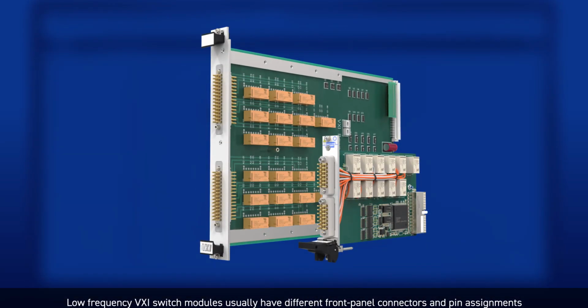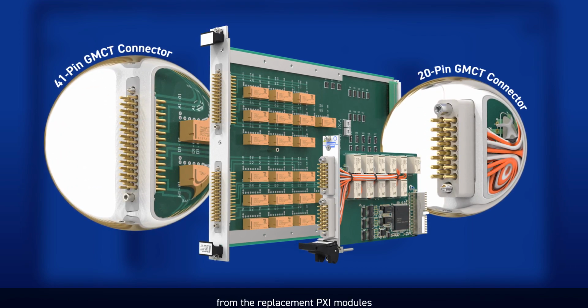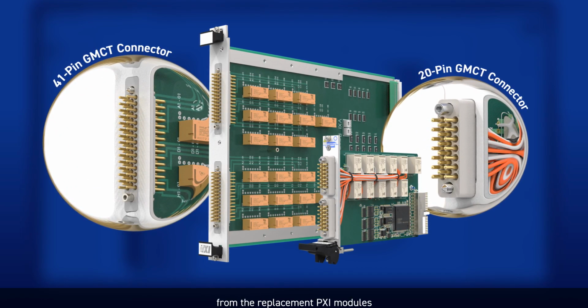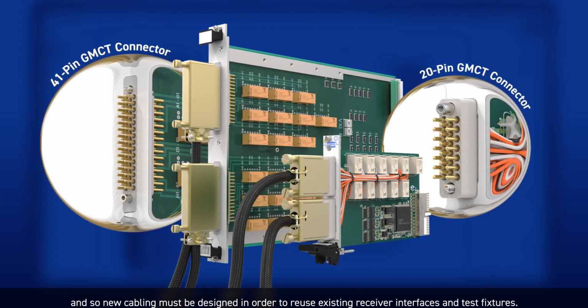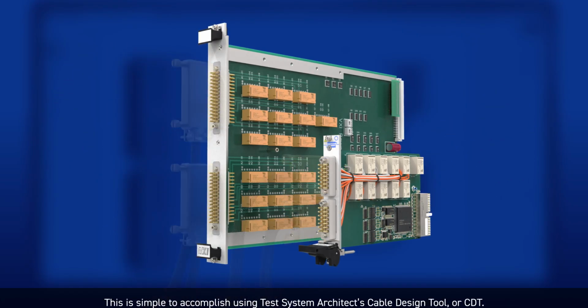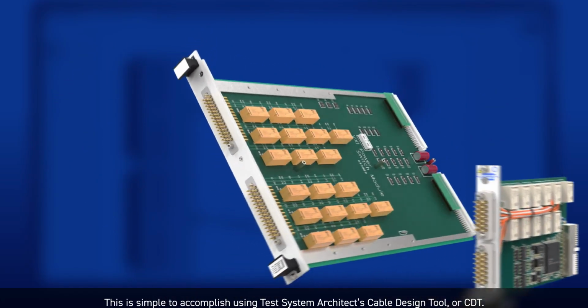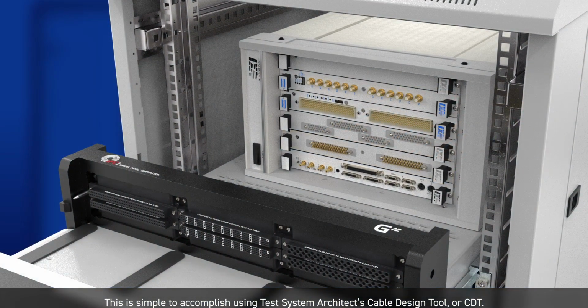Low-frequency VXI switch modules usually have different front panel connectors and pin assignments from the replacement PXI modules, and so new cabling must be designed in order to reuse existing receiver interfaces and test fixtures. This is simple to accomplish using Test System Architect's Cable Design Tool, or CDT.